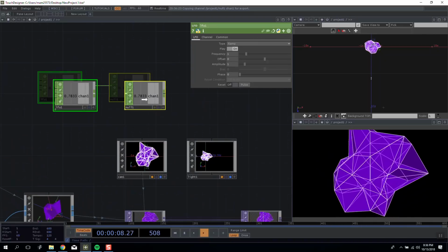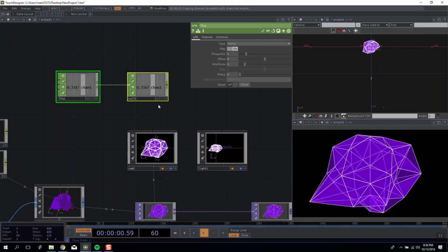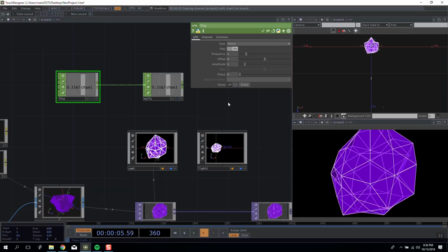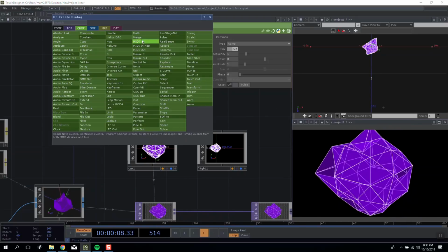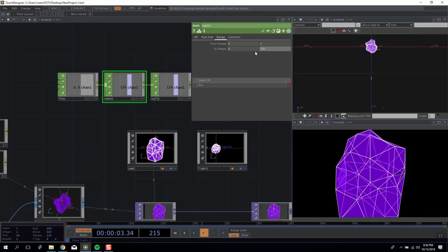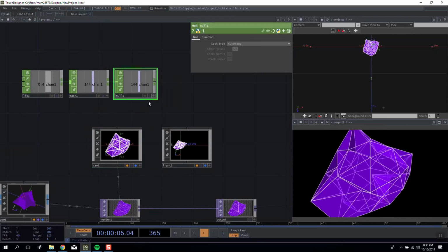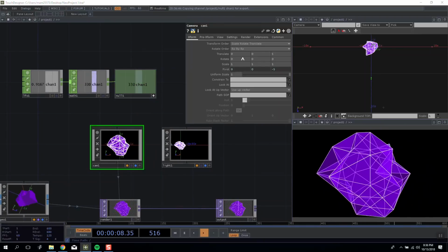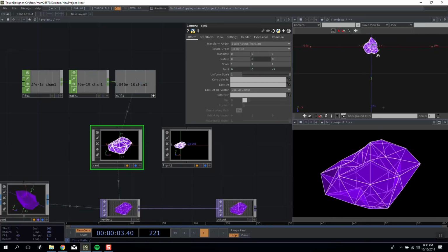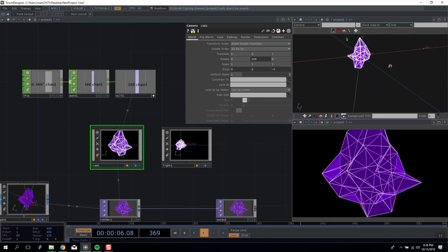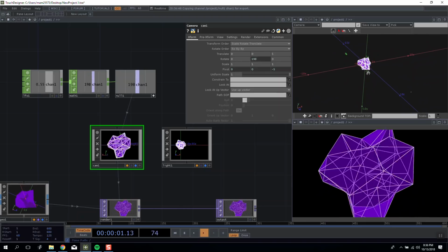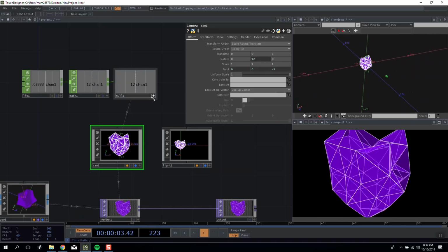So, without going into too much detail of standard grade maths, a circle has 360 degrees in it, and I want to move my camera all the way around this sphere in a second. So I'm going to insert a math, change its range from 0 to 1 to 0 to 360, and then I'm going to attach this parameter into my rotation with a relative reference. So now, if I go back to a perspective view, zoom out a bit, you can see my camera spinning around it. Might be spinning a bit fast, but the idea is there.